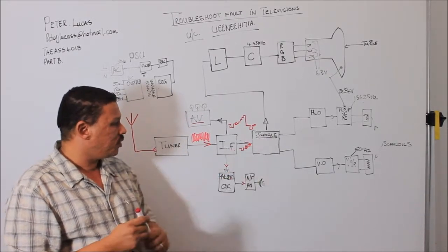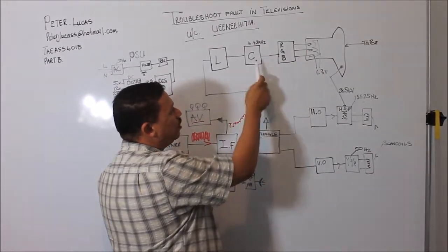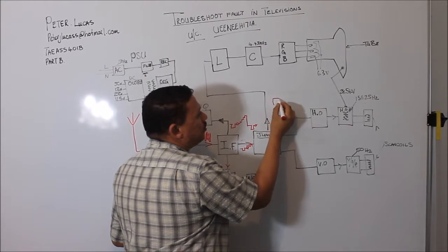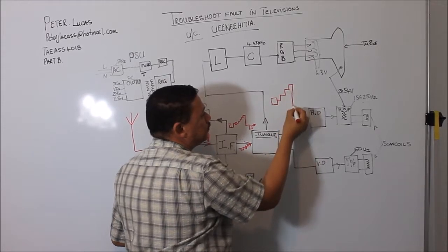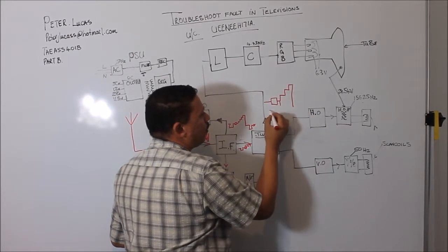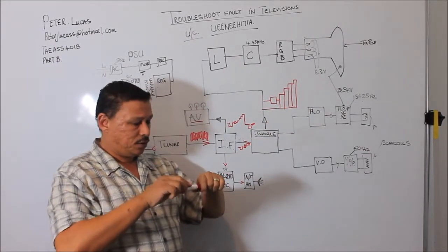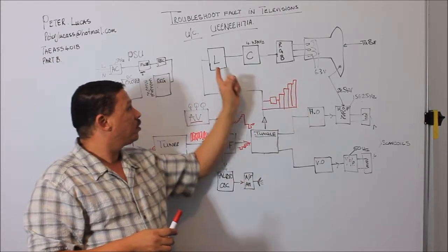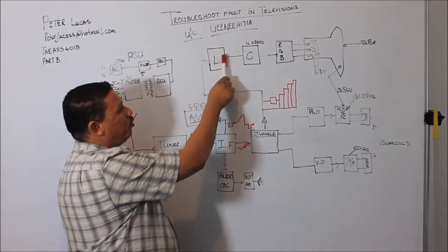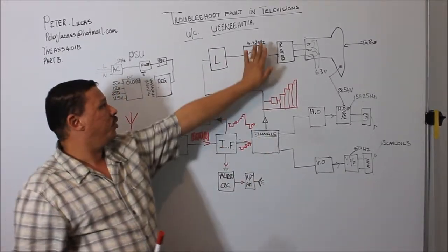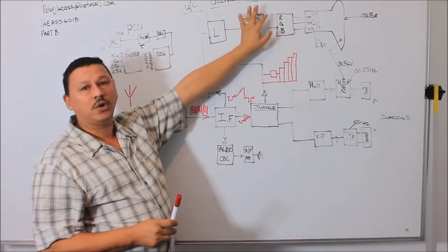So once the signal comes out of here, a certain portion of the signal that goes to the luminance and chrominance circuit would look something like this. This is your color, and this is your chrominance bars, luminance bars. The first thing that happens is the signal coming out of the jungle chip goes into the luminance circuit, and the luminance circuit, without the color circuit, you would have a black and white picture. Black and white television hasn't got color.